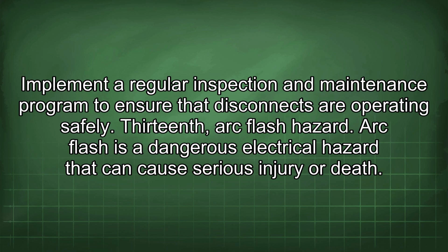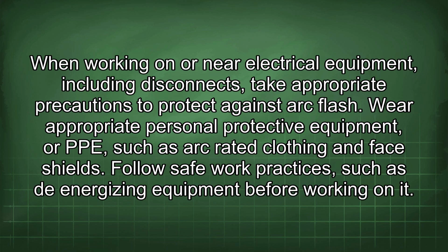13th, arc flash hazard. Arc flash is a dangerous electrical hazard that can cause serious injury or death. When working on or near electrical equipment, including disconnects, take appropriate precautions to protect against arc flash. Wear appropriate personal protective equipment, or PPE, such as arc-rated clothing and face shields.